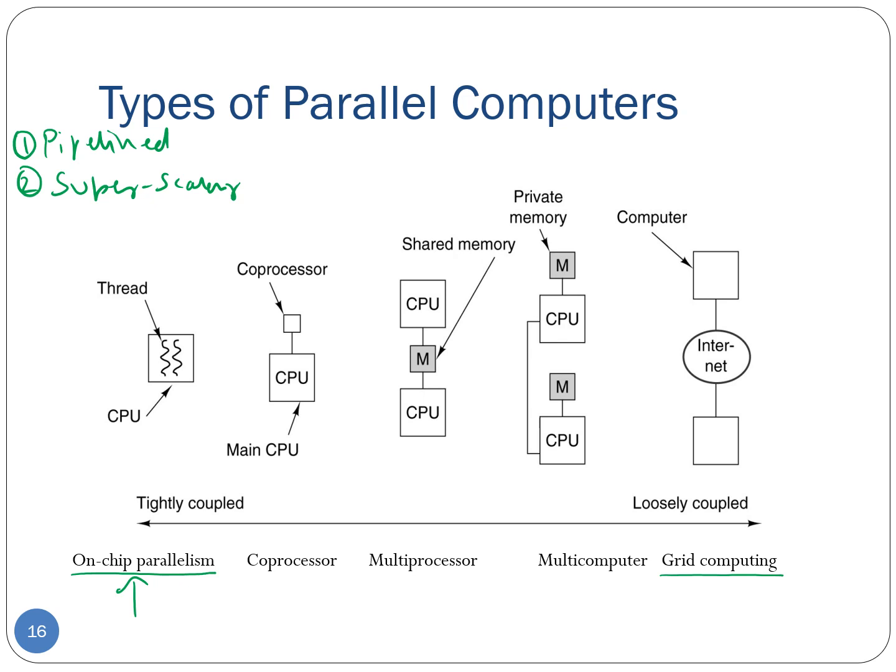Additionally, we can include hardware support inside a given processor so that it can execute multiple threads simultaneously. This is known as multi-threading. So this is the third kind of on-chip parallelism. And finally, on a single chip, we now have enough space that we can have multiple CPUs or multiple cores, right?